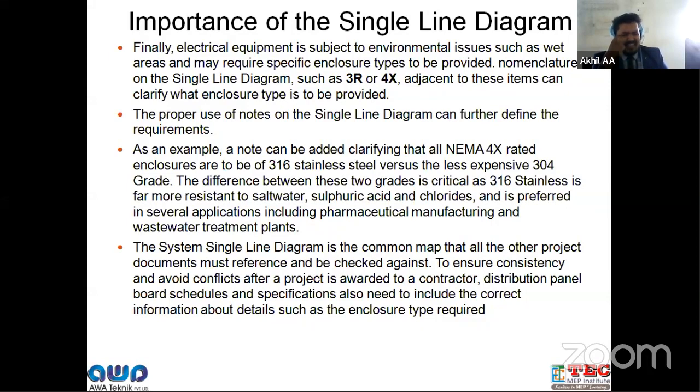For example, if I'm taking a cable of AYFY, this is a cable code for aluminum cable. The conductor is aluminum, PVC insulation, steel strip armored, again PVC outer sheath. That is a cable code representation for an aluminum cable. So if I want A2XFY, A2XFY means aluminum cable, XLPE insulation. So the insulation has been changed.